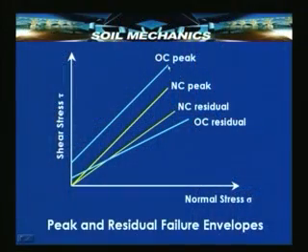The sequence in which the envelope keeps coming down is practically constant and valid for all clays. The over consolidated peak strength is very high, over consolidated residual strength is very low. The normally consolidated strengths lie between these two.